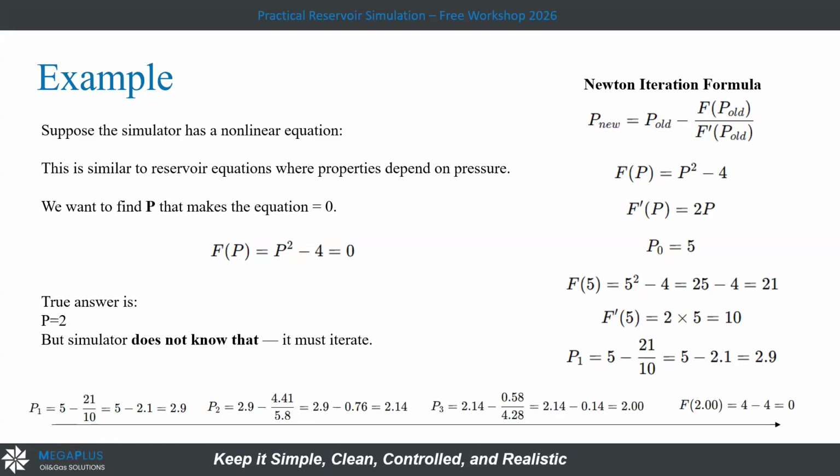So how does the simulator work? It's very simple. If in any equation I have inputs x and y, it will give me an output. But in reservoir simulation, the cell doesn't know the input that it will have. It depends on the output of the neighbor cell, and so on, and this cell's output will in turn depend on that input. So the simulator works with something called an iteration formula.